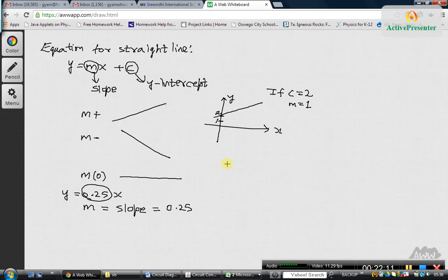So from Ohm's law, you know that if you draw this visual way of representing the Ohm's law equation, if you want to find current, it is V by R. If you want to find resistance, it's V by I. If you want to find the voltage or potential difference across the resistance, it's IR. V is equal to IR. So here, what is the dependent variable? The dependent variable is the current. So you need to find I. So I equals V by R, which can be written as 1 by R times V.